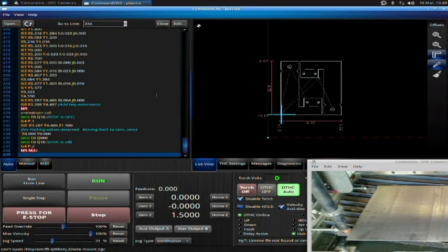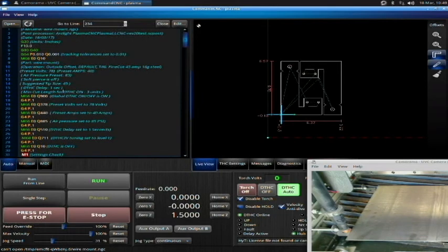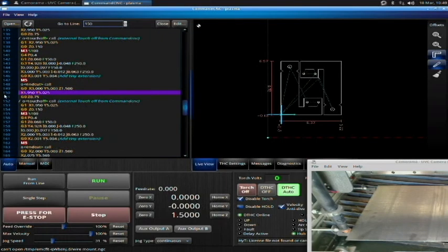Okay, so a few more things about the G-code. This button here is to rewind the G-code, or essentially refresh it from the beginning. That's very important. It makes sure that the machine is read through the code properly. You have a go-to line here. You can tell it to go to a specific line. Okay. Say you want it to go to 150. It went to line 150.